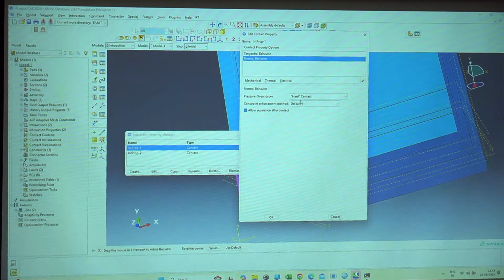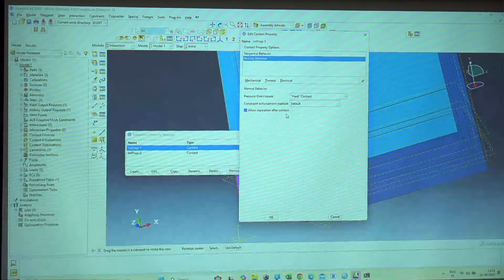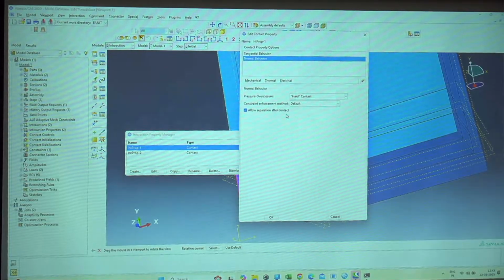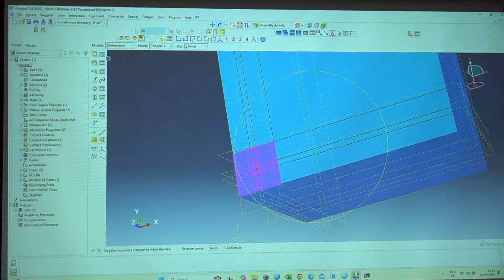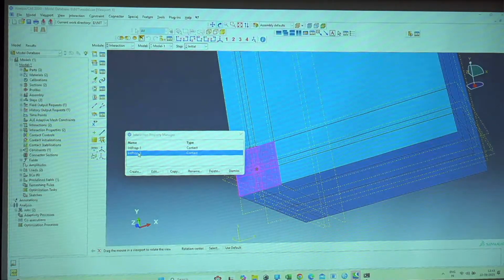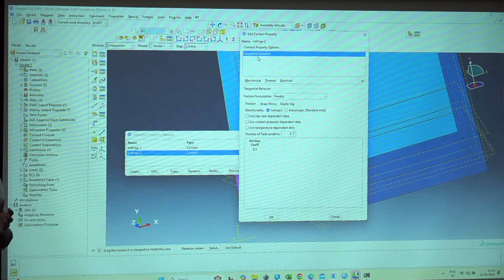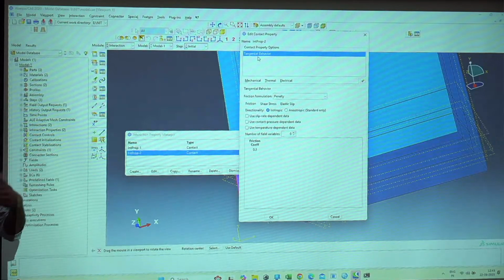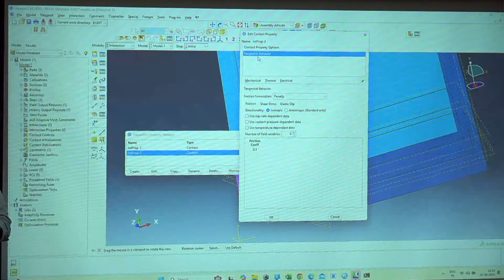So the normal part is hard contact, and allow the separation after contact. As you said, sir, if I apply the lateral load, separation is allowed. It is allowed by default. And for the pile, I used only the tangential behavior. Okay, because my soil is a soft soil, so friction pile is there, so only the tangential behavior will be there. So I am using only this tangential behavior. Okay.